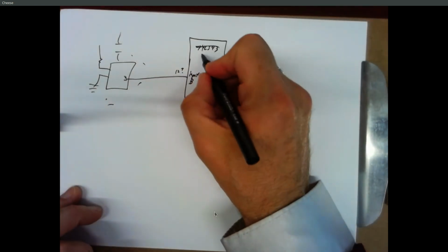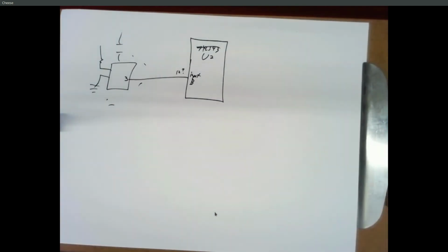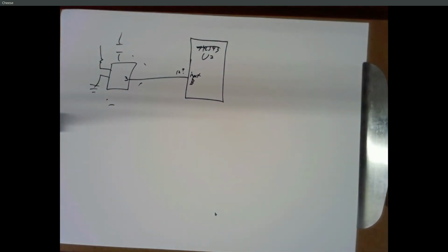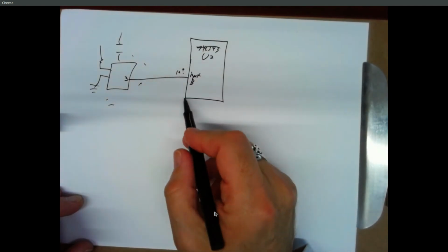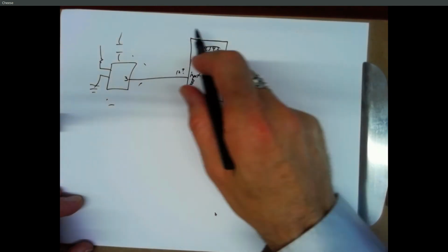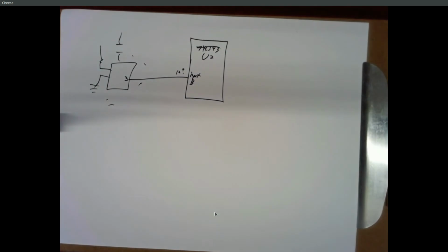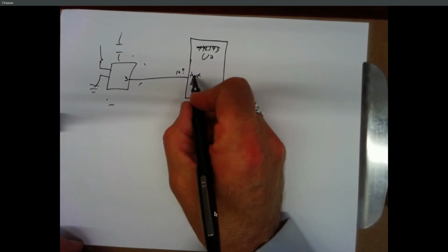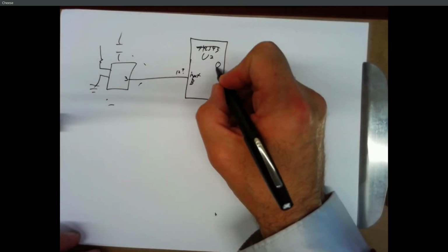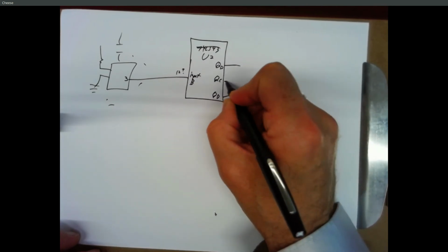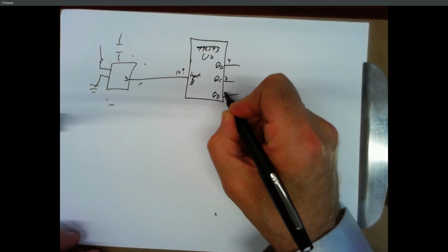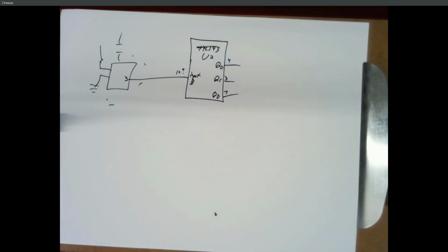Right? And this is going to be, like, U2. And that's specified up in the component ID block. But you don't need to draw this picture 1, 2, 3, 4, 5, 6, 7, 8, 9, 10 and go over to the correct spot, right? You can put this however makes sense. So it's kind of like a really fancy gate, but it's not a standard gate like an AND or an OR. So label what the inputs do where they are. If this is QD, QC, QB, and whatever the pin numbers are on those.